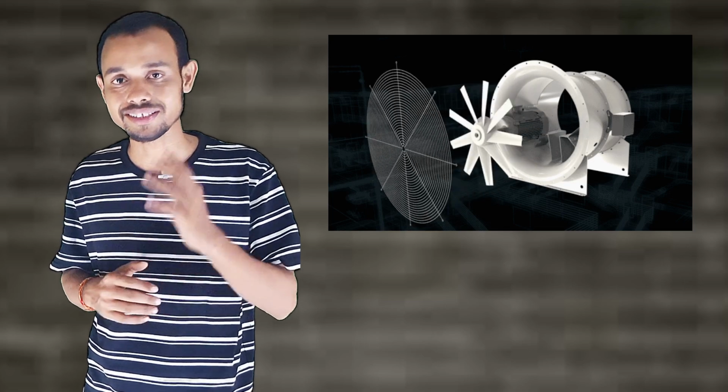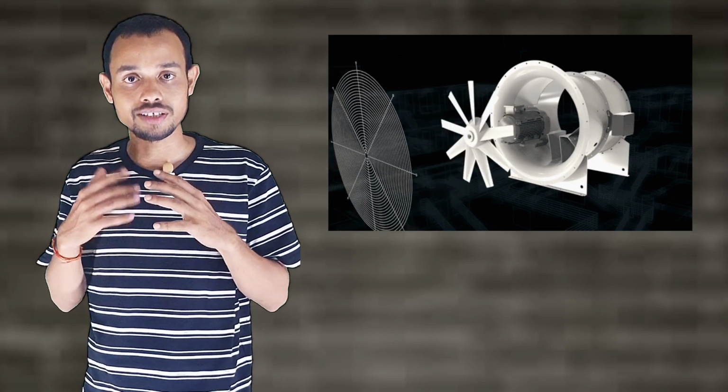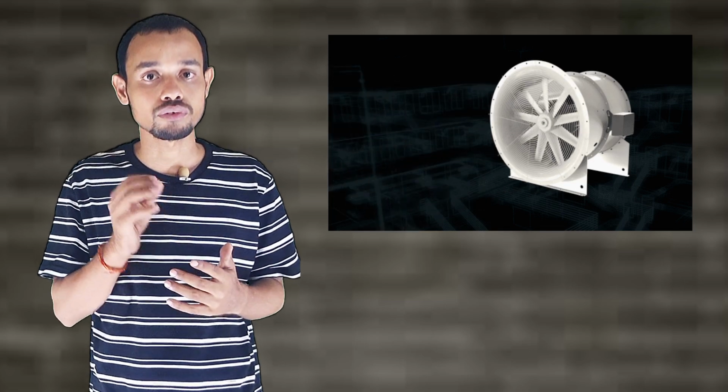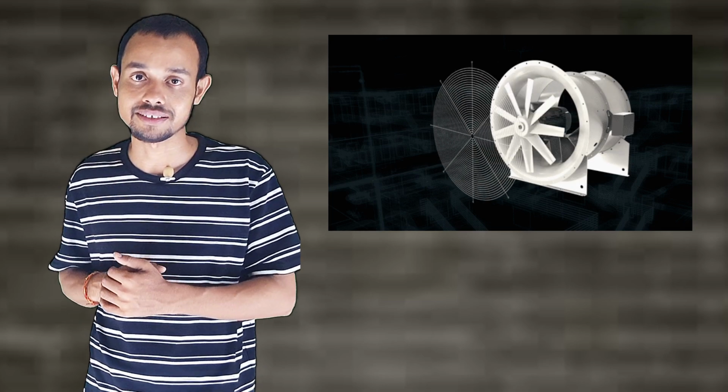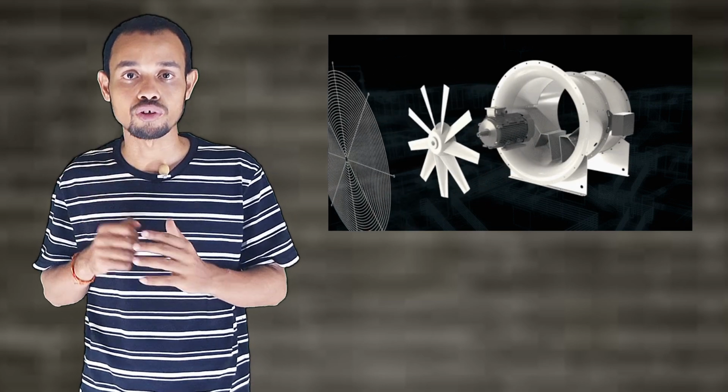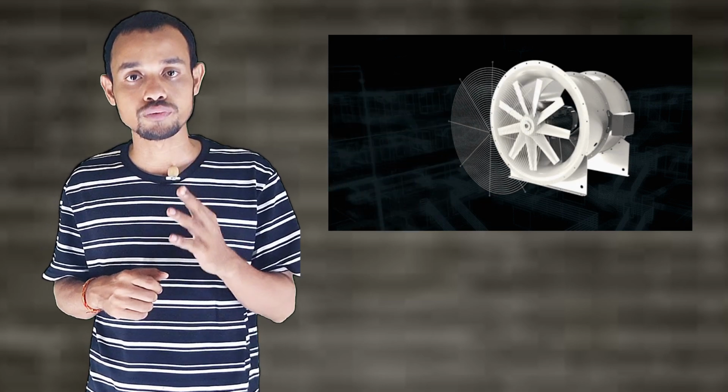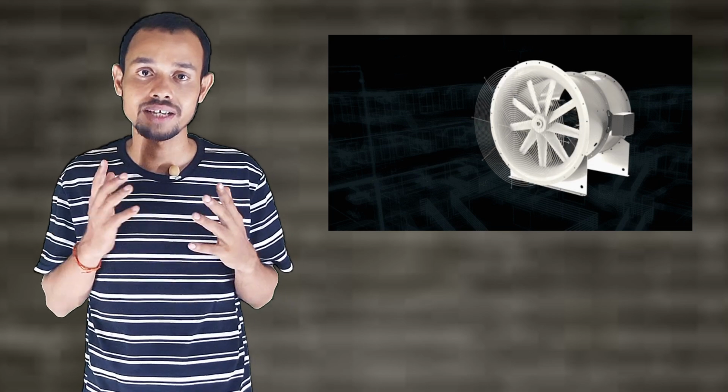Okay, and second is axial fan. Let's see the axial fan. What is axial fan? It moves air in a straight inline direction, suitable for the low to the medium pressure applications, perfect for the high volume air movements. Okay, used for the cooling tower, ventilation rooms and the wall fans.